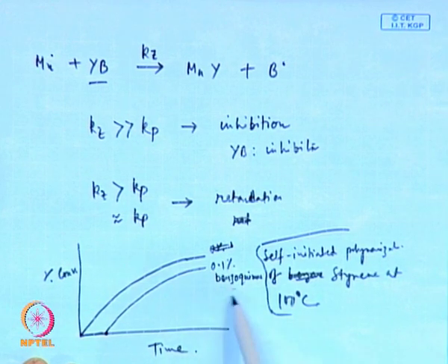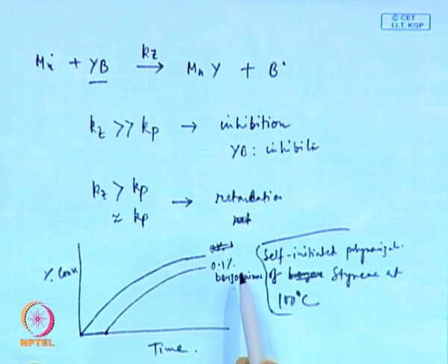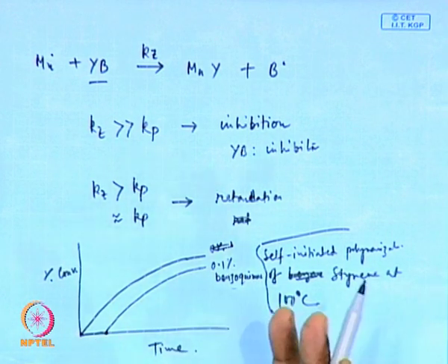Now, this is a typical example of how common monomers are shipped or stored. Most monomers, when they are shipped between different countries or locally, are stabilized with a small amount of inhibitors, for example hydroquinone or benzoquinone, because they should not self-polymerize either by a little heat from the ambient or by self-initiation reaction.